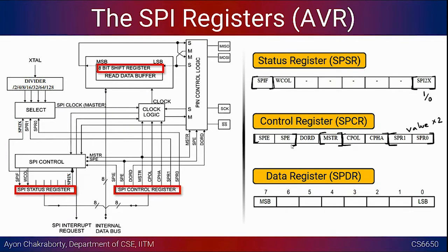Whenever you look at the data sheet, you first have to know what your hardware-software boundary is, like what the different features the peripheral has, and what the avenues are to access those features. And those features have to be directly manipulated using some registers, some configurations, right? So that is how you write the driver, right?